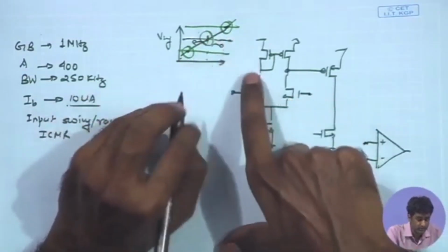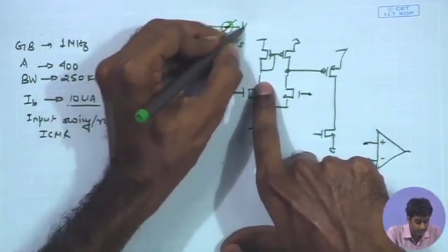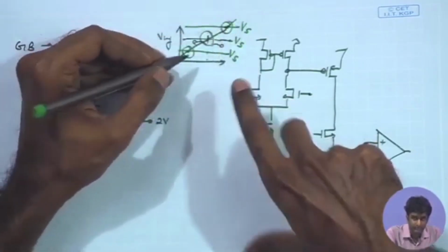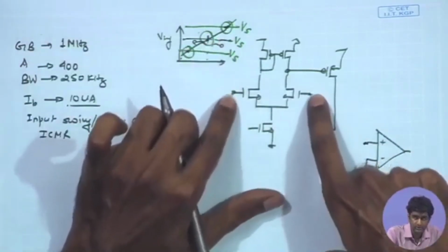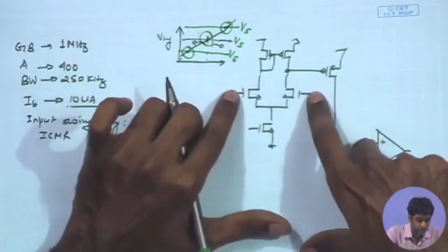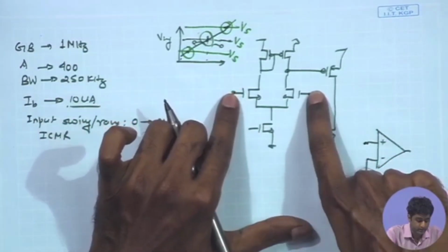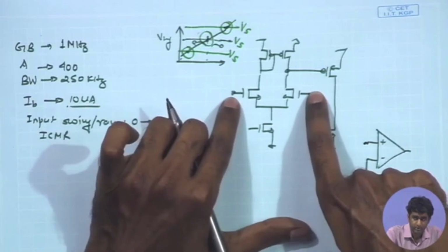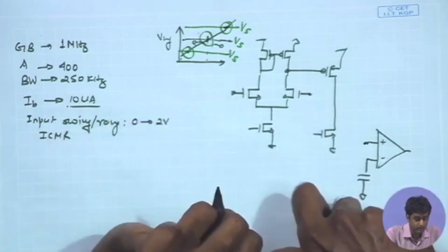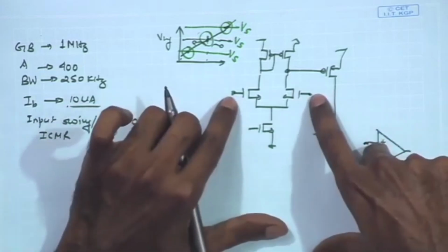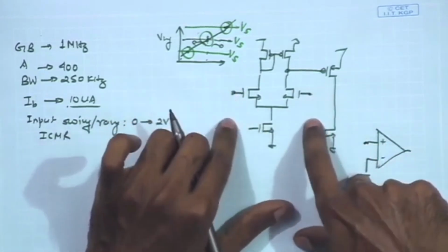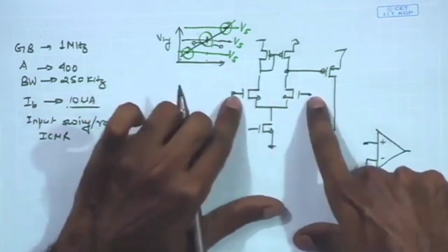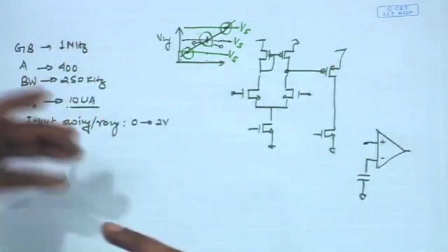The sample signal Vs and the ramping V ref, whenever they are getting close together, that means both the inputs of the comparator are close together, and we are supposed to detect a small difference or change in polarity of V in 1 minus V in 2 at that particular point. And for that we must make sure that even for low input voltages as well as very high input voltages approaching VDD, it should be working, and that is the definition of input common mode range, right.